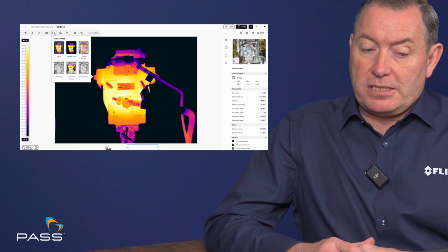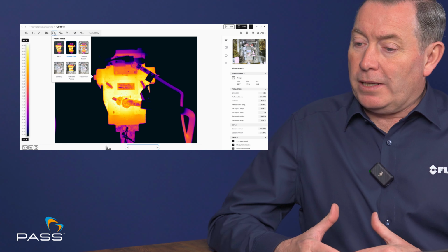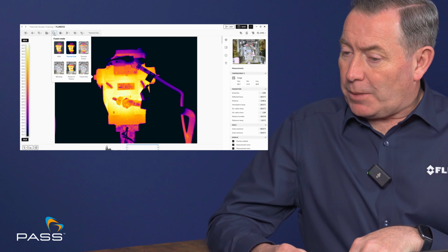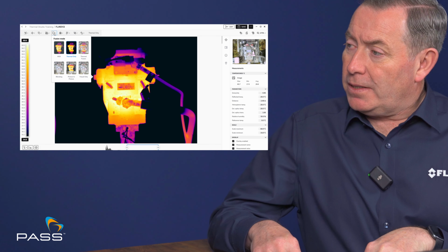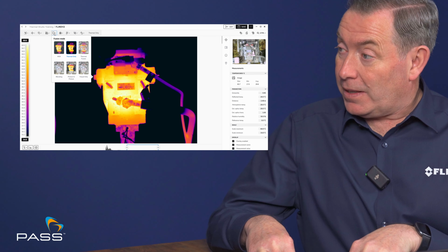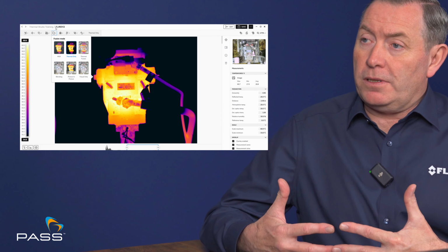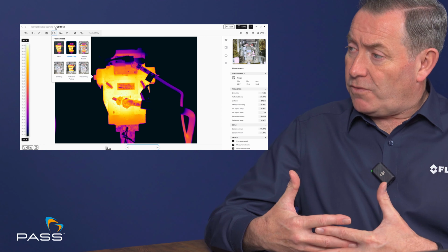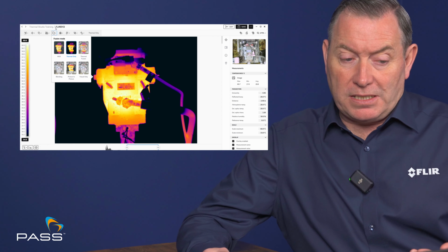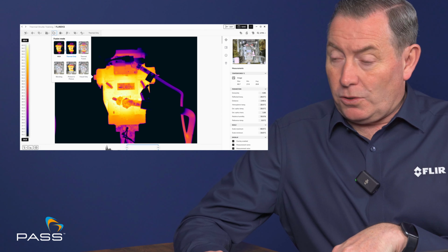These are modes which are available. As I talked about previously, when you capture an image, or a thermogram, it's capturing two images at the same time: one through the digital lens, the visual image, and one through the thermal lens, which is the infrared image, the thermogram. And then you can manipulate those images using the software to highlight areas using both images. For example, we have a feature on some cameras called MSX.